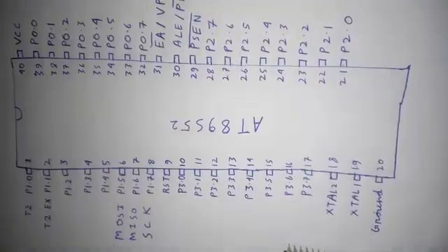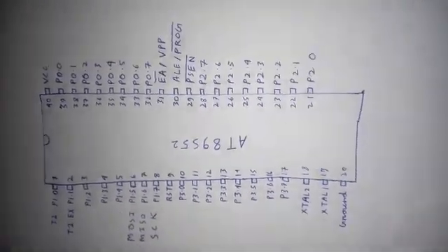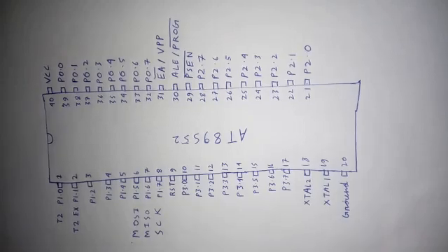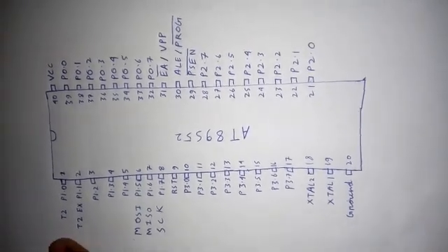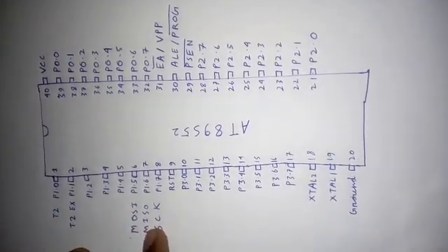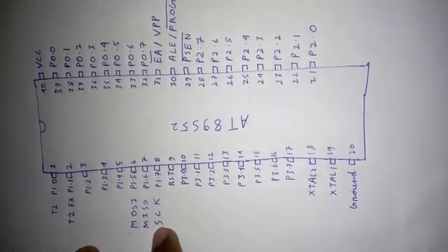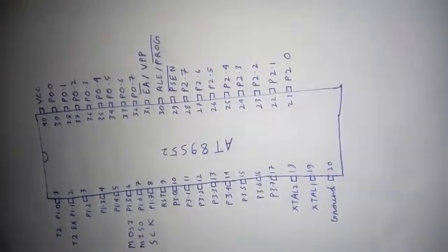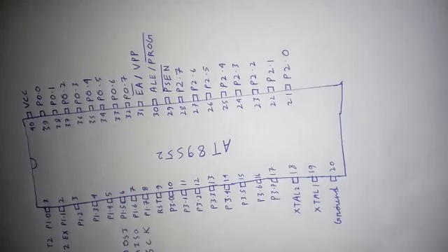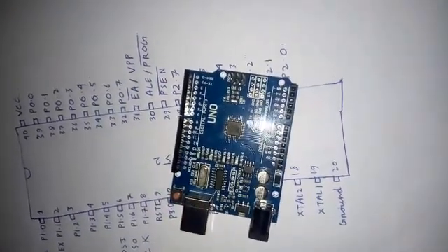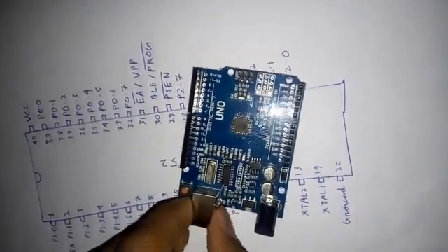Hi, in this video I'm going to show you how to program 8051 chip. This is AT89S52 chip. The pinouts of this chip is as shown. We need that MOSI, MISO and SCK for our programming, and in this case we will be using Arduino to program that.